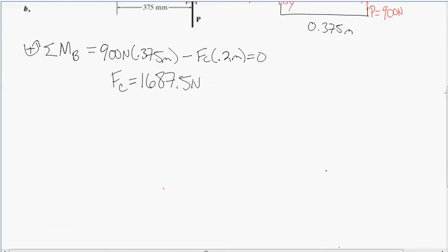So now we're just going to draw a separate free body diagram just for the clutch and the crank. And we know that the contacting surface of the clutch is at an angle of 15 degrees from the horizontal. There'll be some contact force along the surface. It will be like a distributed normal force along the surface, along the entire contacting surface.